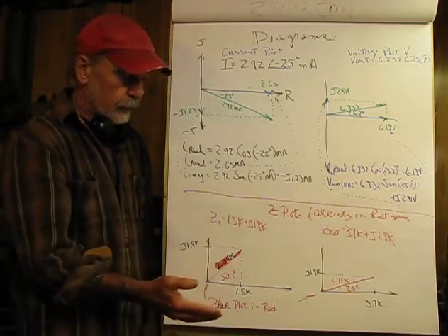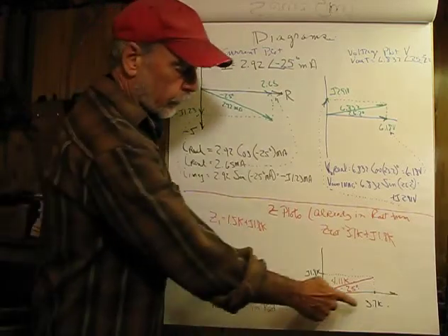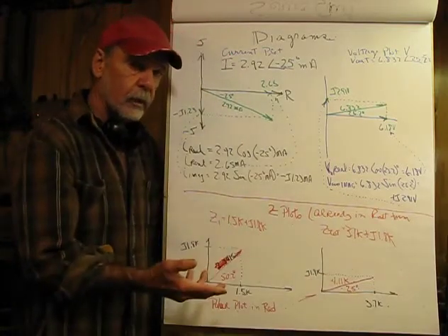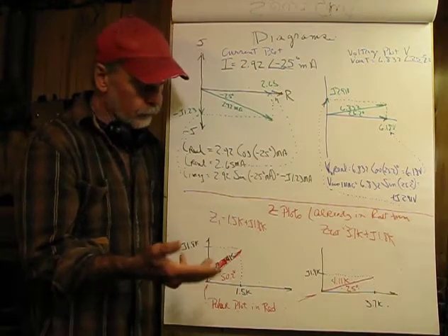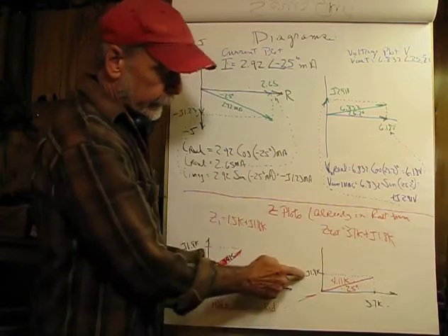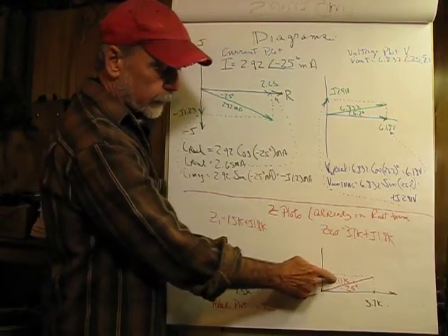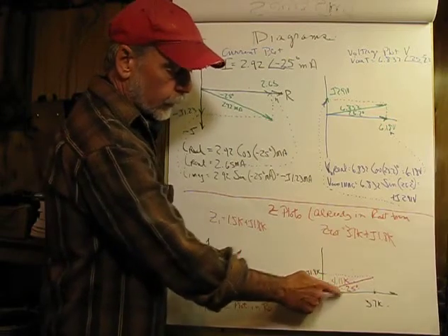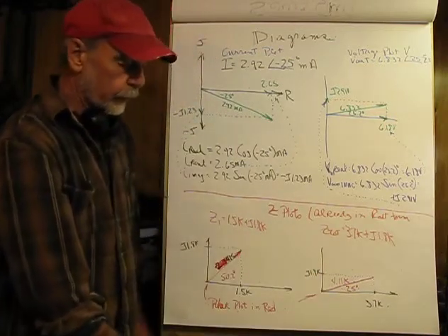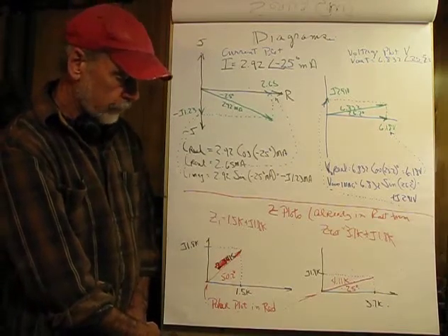And then to do Z total, we also have that in polar form. If you recall, 3.7K was the sum of the two real components of resistors. Again, J 1.8, and connecting the dots gives us the total impedance of 4.11K, and the 25 degrees sitting between the real axis and the total impedance.